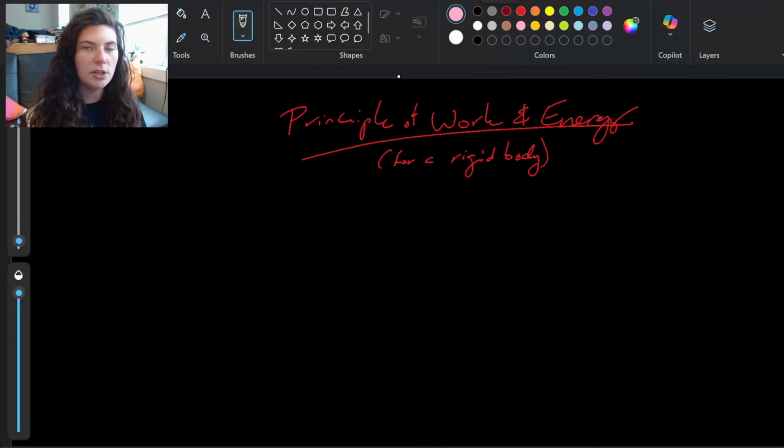So in our last video, we talked about how our work and energy look a little bit different when we're dealing with a rigid body instead of a particle. With that, we said that for work, we now have to take into account that a moment can do work. That's really one of our new things. The other thing to take into account is that our kinetic energy equation is just a little bit different. If our moment does work, then that's going to be our moment times whatever angle theta that displacement is caused.